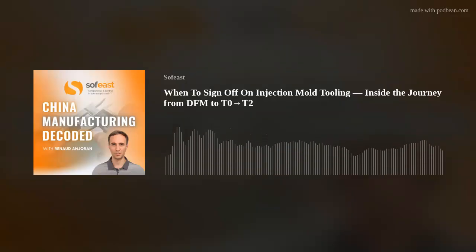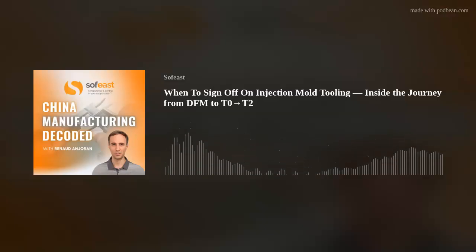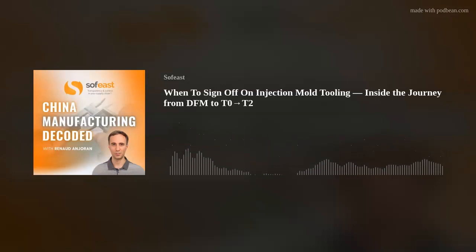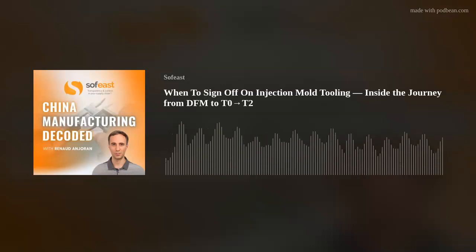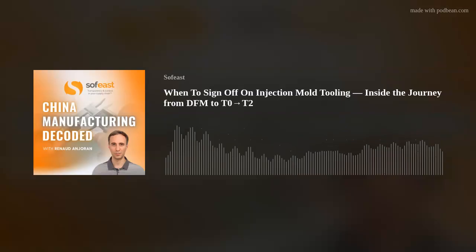Once those adjustments have been made, we then put the tool back into the injection mold machine, and we will run the correct polymer. In other words, we get rid of all the regrinds, and we will use virgin material, and we will pump these products out, and maybe we'll be producing 10, 15, 20 units just from a look-see point of view. This is known as T1.